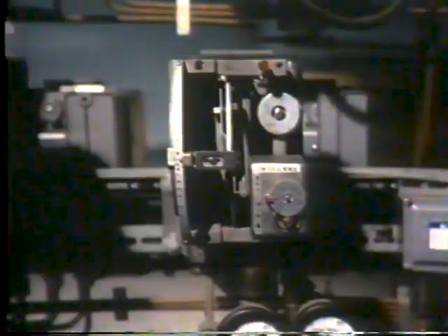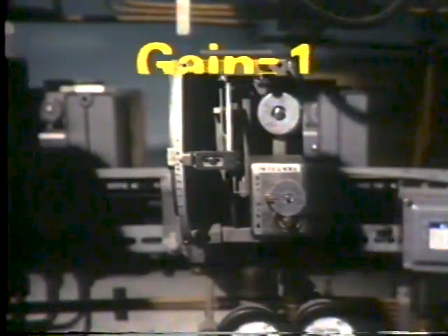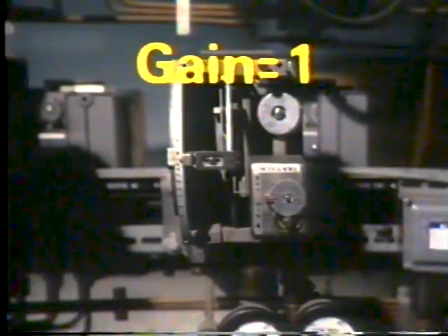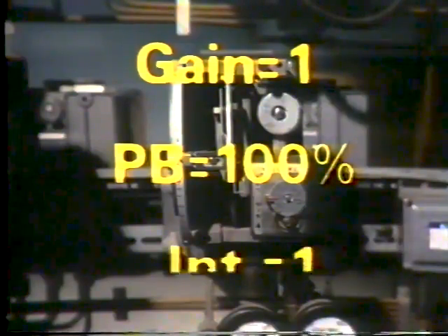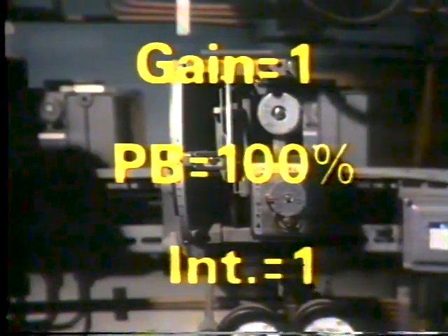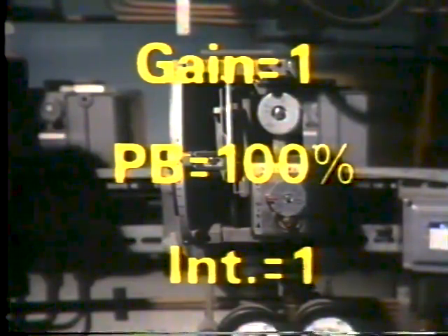The system's controller is a typical PI controller. Its gain is normally set to 1. This is a proportional band of 100%. And the reset control is normally set at 1 repeat per minute. This means that the controller repeats the amount of proportional output each minute the cooling water temperature is away from the set point of 85 degrees. The system control loop operates on a pneumatic pressure range of 3 to 15 psi.